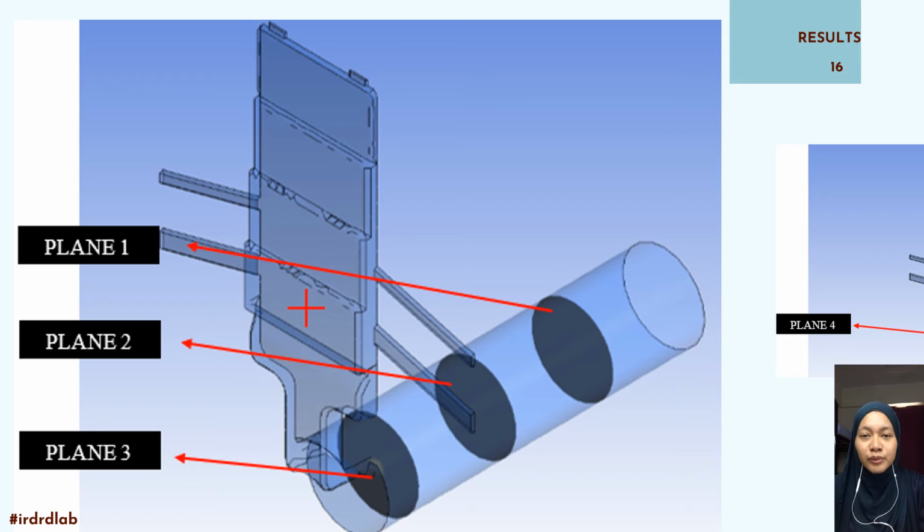The molten metal input velocity is very crucial in determining the molten metal velocity streamline pattern inside the cavity. On the standard mold design, the parametric machine value for entrance velocity of molten metal, specified by Kyokuto Die Casting, Japan, is 2 meters per second. 2 meters per second is a reasonable speed that prevents molten metal from backflowing into the mold cavity, decreasing entrapment and increasing industrial efficiency. The total length of the plunger is 250 mm.